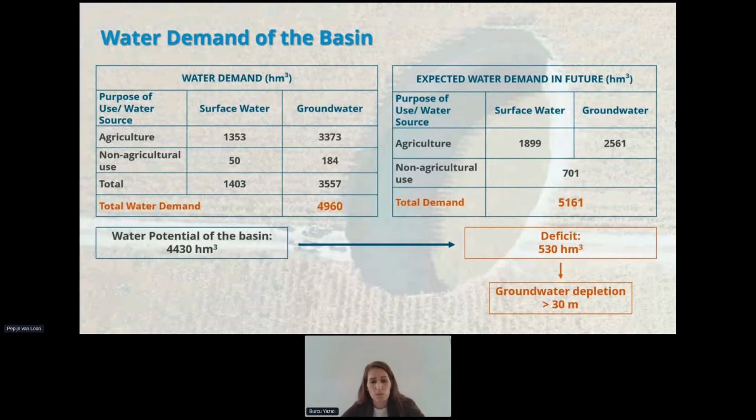So far, unsustainable irrigation methods and unlicensed wells have led to a groundwater depletion of over 30 meters over the past decades, and this also resulted in the formation of sinkholes in the basin due to its karstic formation. You can see one of the sinkholes as the background picture of the slide. We have around 600 sinkholes formed in the basin due to over-abstraction of groundwater. Apart from these issues, climate change models also predict a 20 to 30% drop in precipitation in the basin. For these reasons, we have to urgently revisit our agricultural practices in the basin and also seriously take into account water reuse options.